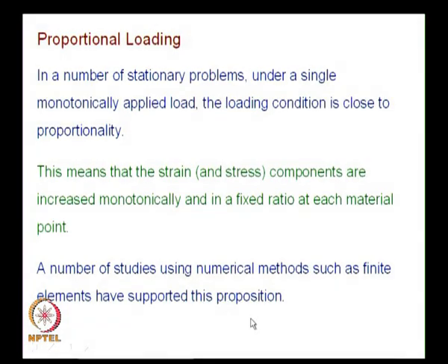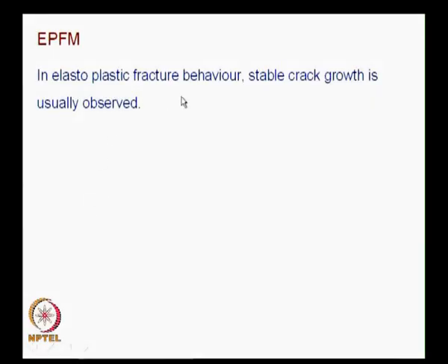See, in the whole of elastoplastic fracture mechanics, you have to look at proportional loading. That is how you justify the applicability of J, at least approximately. You have to remember, it is not an exact representation. Approximate solution is good enough. As long as I am able to solve the engineering problems, even approximations are welcome. You have to take it with a pinch of salt.